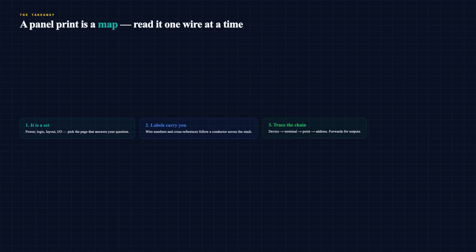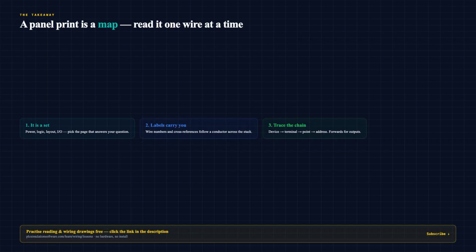So here's what to walk away with. A panel print is a set, not one page. Power, logic, layout, I/O. The symbols are simple, but the wire numbers and cross-references are what actually carry you across the stack. And every signal is just a short chain you can trace. Device to terminal to point to address. Get that? And the wall of lines becomes a map you can navigate one wire at a time.